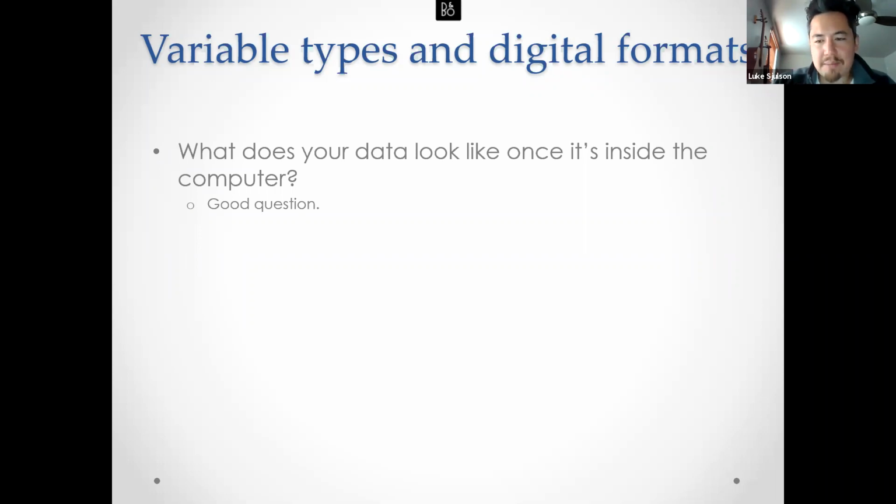So the Intan preamps actually bandpass filter the signal. The low pass filter filters out everything above something like 8 kilohertz. I don't remember the exact number. And then the high pass filter goes down to something like 1 hertz or 0.1 hertz. I was wondering because I get both signals at once, so it seems like it would be bandpass in this case.